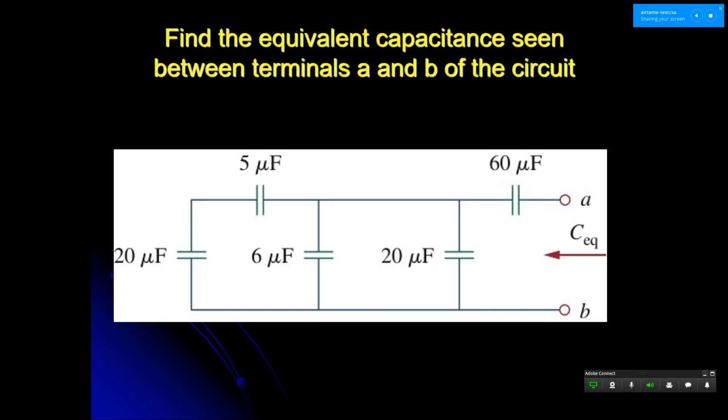All right, here we go. This is basically a resistance circuit. They try to find the equivalent resistance. Here I'm just doing the opposite. Instead of finding the equivalent resistance, I'm asking to find the equivalent capacitance. It's totally the same idea, right? You add the series ones first, and then you add up the ones in parallel, and voila, it's done. So let's go ahead and do that.